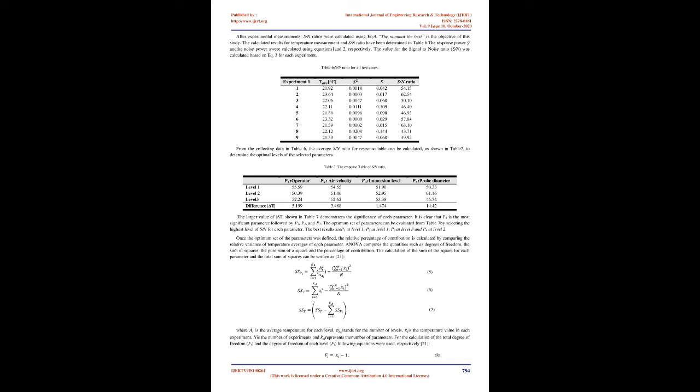Table 3 shows the temperatures and resistances for each sensor used to find the values of thermistor constants A, B, and C based on EQ.4. Finally, by using the DAQ system and EQ.4, the values of resistance and temperature are determined as follows, where T is the temperature, R is the resistance, and A, B, and C represent 3 different variables.